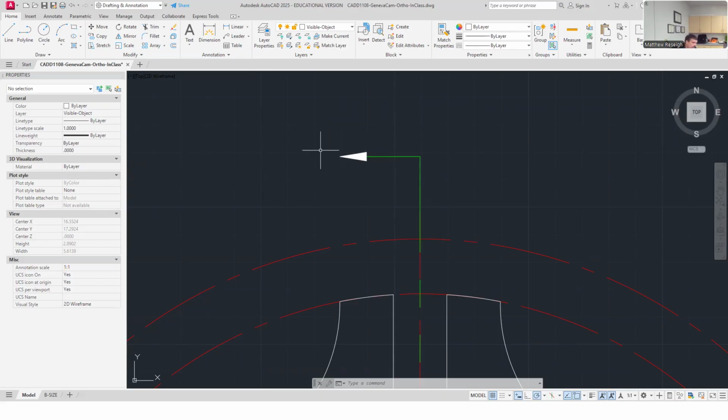So when you choose polyline and width, it's going to want to know a start width and an end width, and then how long it is. So it's like 3 inputs on this arrow essentially. And so it was 0.08 to start, 0 to end, and then it's a quarter of an inch long. So technically, if my drawing was 1:1, I could just leave that alone. This doesn't fit on my B-size sheet at 1:1, so I need it to be annotative, essentially. I need it to automatically adjust the size.